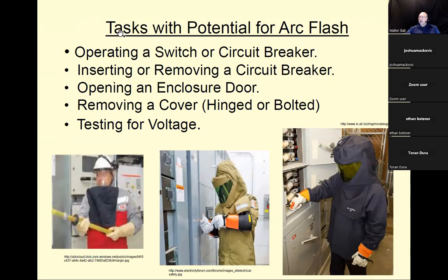All right. Tasks with potential for arc flash. So what would be the work that we would have? Operating a switch or a circuit breaker: there's a potential of arc flash. Inserting or removing a circuit breaker can produce an arc flash.